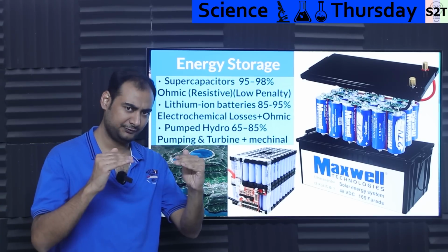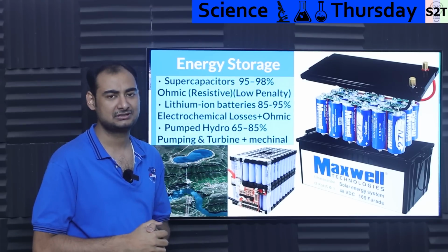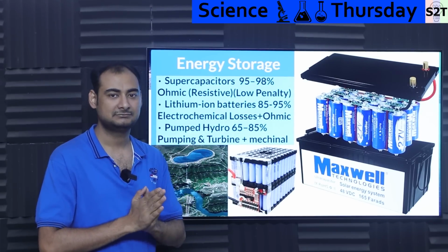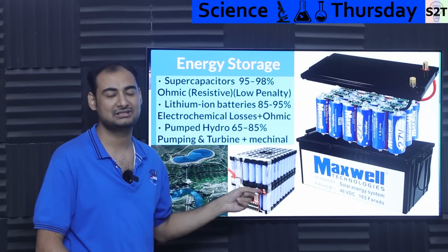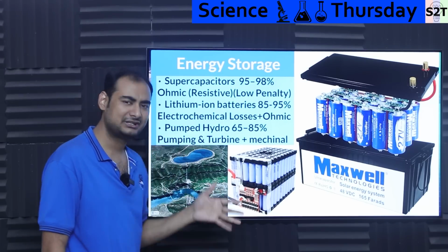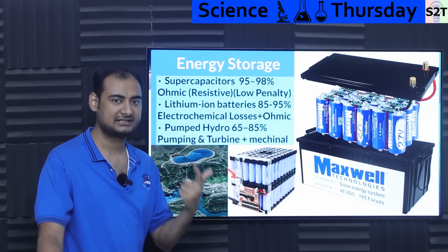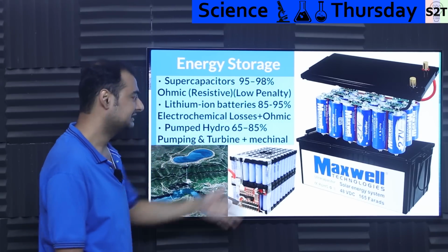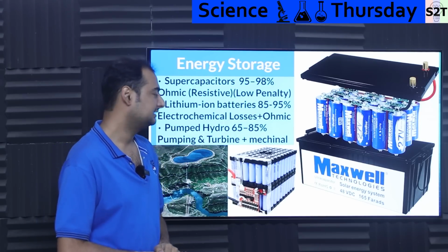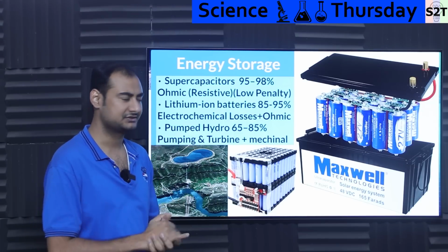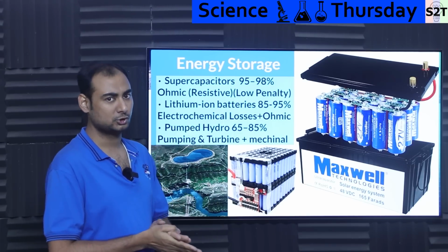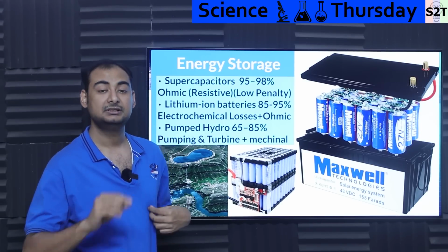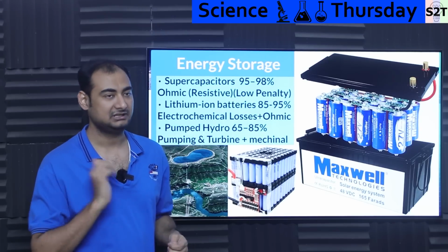So we are almost at a point, and that's why you will no longer see people asking, okay, what if we put in a supercapacitor? The gap is so narrow, and again, this does not have a high self-discharge rate. So more than enough times, if you have a good battery, good cell chemistry, good geometry, good packaging efficiency, you do not need this anymore. Again, that's why this company was sold to Tesla. Tesla bought this and took the technology of dry electrode coating, and they are using that for the big cells right now. And that's how they also upgraded the cell design from tabbed to tabless.